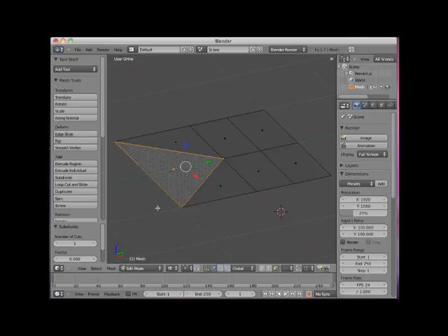I'll then subdivide it. Each of the three edges was divided in half, creating four triangular faces inside the selection. Since two of these edges share an adjoining face, each created a new edge to justify the division of the face. Many times Subdivide is used to create faces in a desired location so that they can be extruded into more complex shapes.